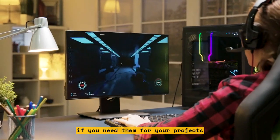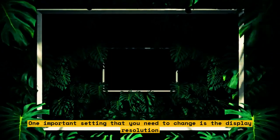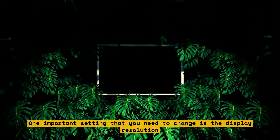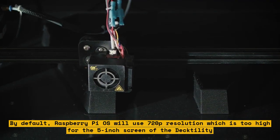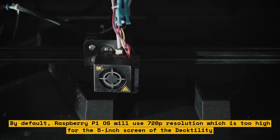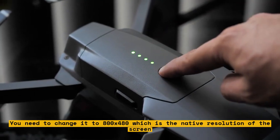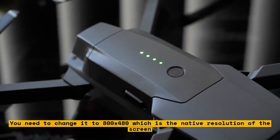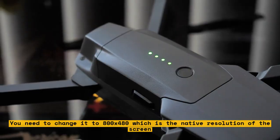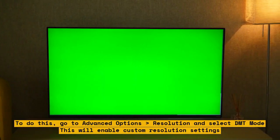One important setting that you need to change is the display resolution. By default, Raspberry Pi OS will use 720p resolution, which is too high for the 5-inch screen of the Decktility. You need to change it to 800 by 480, which is the native resolution of the screen. To do this, go to Advanced Options, Resolution, and select DMT mode. This will enable custom resolution settings.